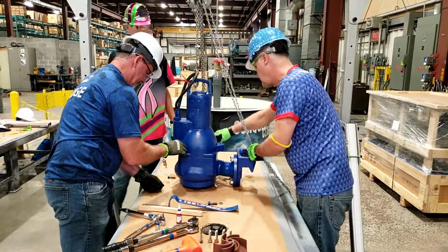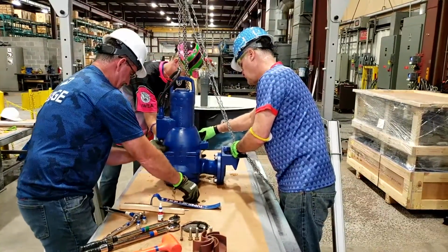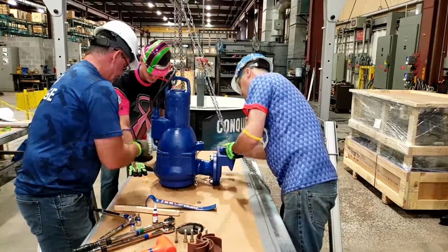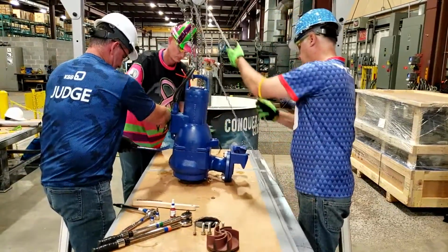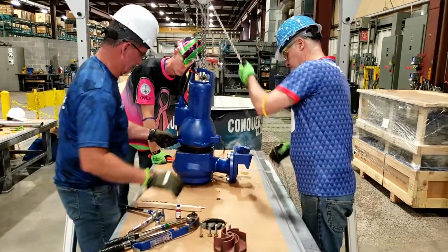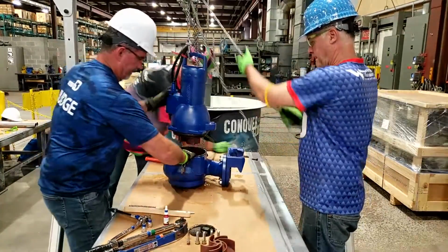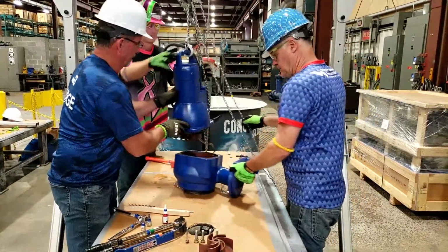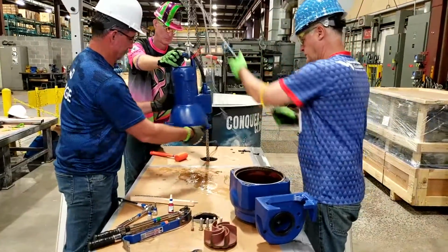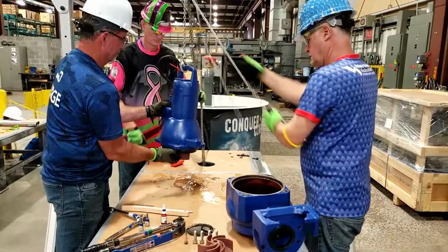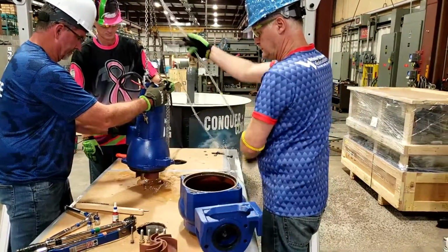While lifting the pump out of the volute, using the chain hoist, you must use the dead blow hammer and/or crowbar to help separate the volute from the pump. The pump shall not be lifted any higher than 2 inches off the table to separate the volute and pump using the dead blow hammer or crowbar. Note, do not place any tools, hands, fingers underneath the pump while performing this action, as they will get damaged or hurt when the volute drops.